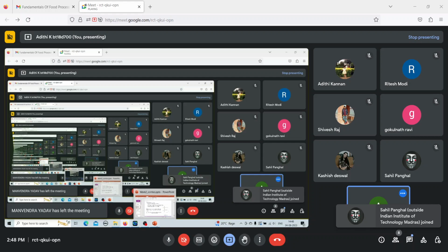So here you can see that the stress is slowly decreasing with time, and the time at which the stress becomes 36.8% of the initial stress, that is, this is the initial stress sigma naught and it slowly starts decreasing, the time at which sigma is equal to 36.8% of sigma naught is your relaxation time, and that is the numerator for Deborah's number.